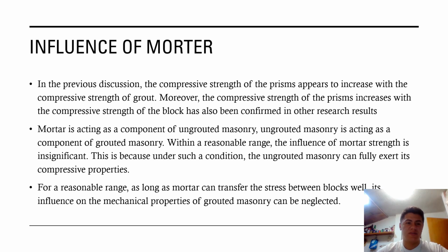Influence of mortar. In the previous discussion, the compressive strength of prisms appears to increase with the compressive strength of grout. Moreover, that the compressive strength of the prisms increases with the compressive strength of the block has also been confirmed in other research results.